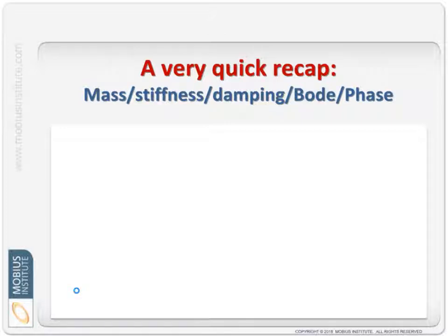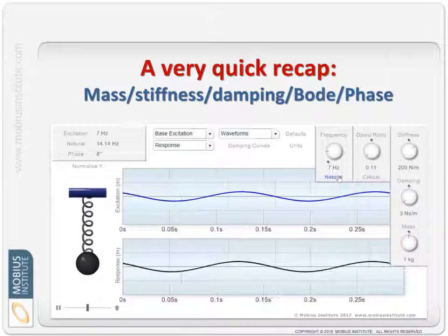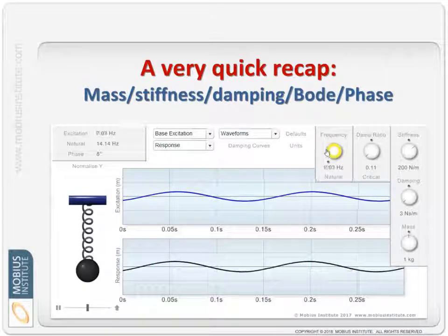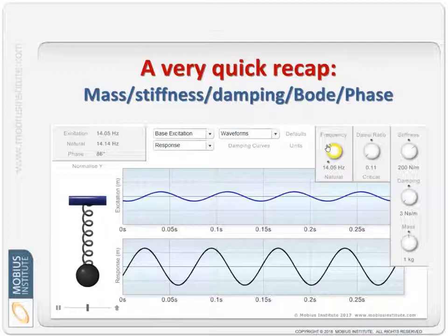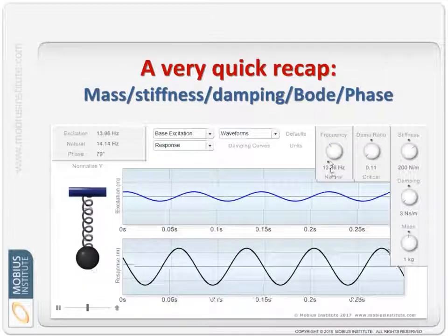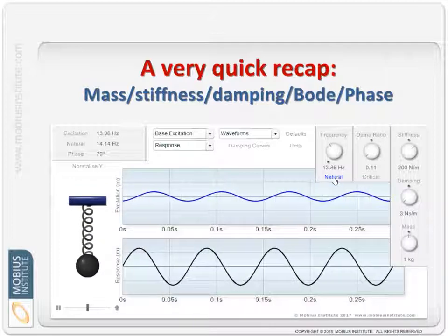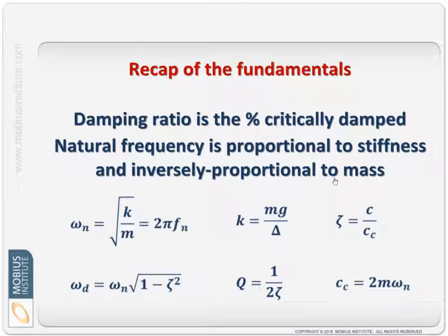We can also then drive that system, and in this instance, if I run it below the natural frequency, we don't get much vibration, but when we go right at the natural frequency, we get a lot of vibration. So look, it all depends on the amount of damping and so on. We see a certain phase relationship. We can look at the frequency response functions, but we'll do all of that during the presentation. There's a lot to know.